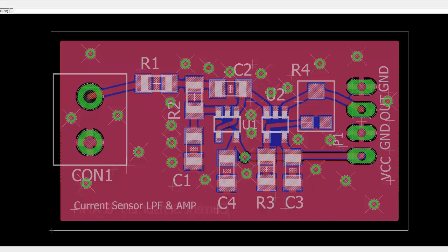And once again, this is important because you want a uniform ground from a potential standpoint, and you also want a nice big ground to block EMI. And then I use these vias all the way around the circuit. These vias are tying the two ground layers together, top to bottom. And this further helps to guard against EMI around these analog circuit runs. Okay, well that's the simple layout. In part 3, we're going to build this up and actually test it.